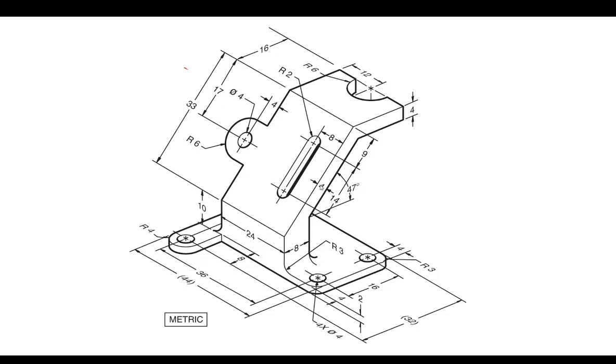So I'm going to choose my order of operations of how I'm going to extrude this object. And looking at this, I see that there is some complexity that lends this to maybe one solution being better than the rest. If I look at this sort of bottom face, I can't really capture this angle face right here. So I can't really use the bottom face as my first extrude. Also looking at maybe the top or the back face or the front face, I don't see an obvious extrusion.